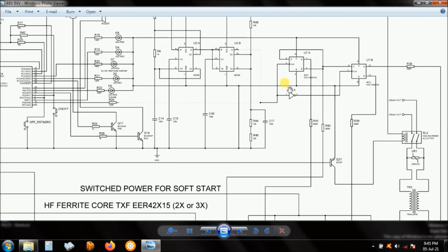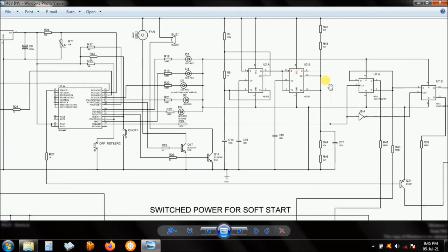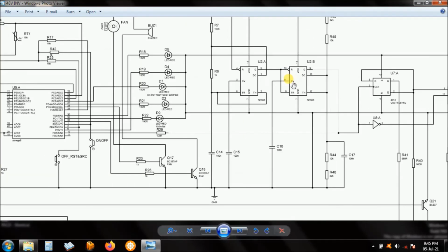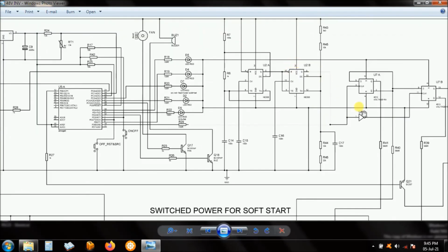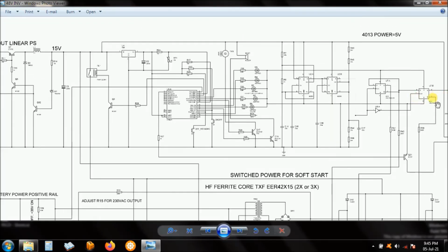But how you connect them between this output and that output is determined by whether you are inputting high pulses or low pulses. For my design I think this is evident, but in most designs pin number 2 and pin number 13 are connected to the high MOSFETs. So I think that's basically what is happening with this circuit here. It's simple but very tricky. You must know what you are doing with your signal here, so that you determine how you are going to connect these ones.